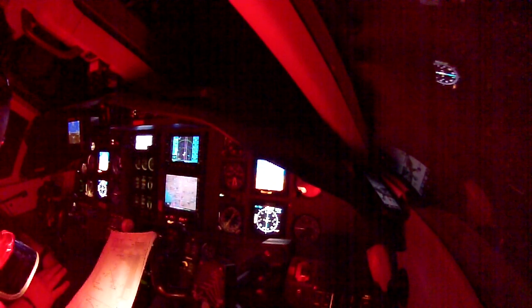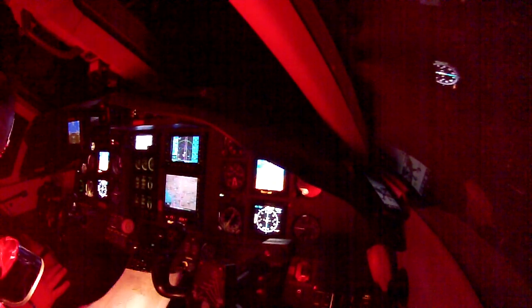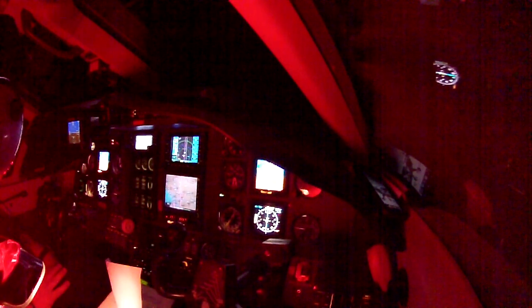So going into Belmar, you don't have WAAS approach, you don't have ILS approach, you don't have precision approach. All you have is non-precision approach, okay? So you're down to 1 mile visibility. You can't go below 1 mile. Maybe runway 32, still 1 mile. VOR Alpha, still 1 mile. So no matter how you look at it, you cannot go precision. You don't have the ability to go down to half a mile visibility on the approaches into Belmar, okay? So 1 mile visibility.